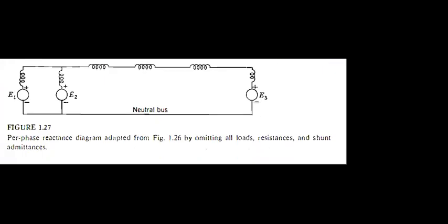This is the reactance diagram, right? What's your question? Yes. Student: Sir, why did we ignore the load, resistance and shunt? Why did we remove them? Regarding that reactance information, the reactance diagram we can sometimes consider as the positive sequence network, which has only the generator information, excluding all the other information. Generator, how many generators are there, and here is the transformer and the line.